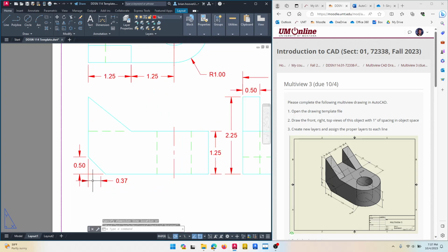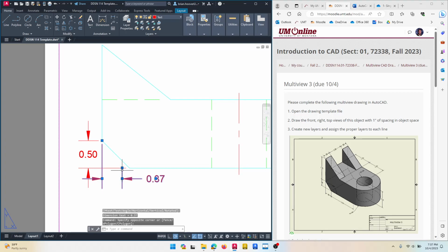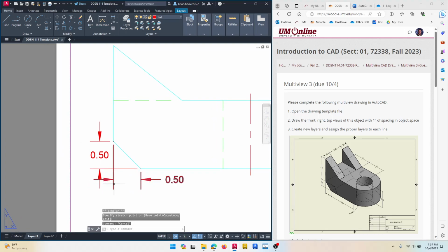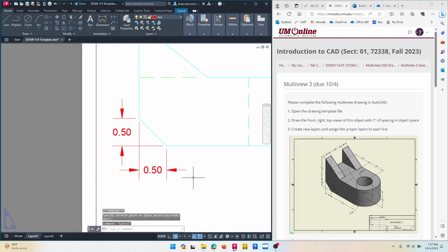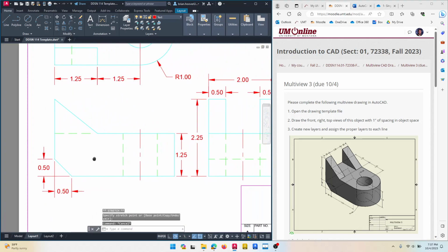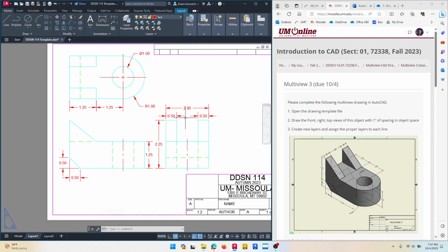And this is an interesting one. You can cross those lines. These extension lines can cross. That's acceptable. Move those out a little bit. See if that actually goes back in there. That works. So I think that's it. I could also add, if I wanted, this 2 over here. That would also be acceptable. Oh, that 1.75, I'll add that as well from here to here. Snap that. So that looks pretty good.